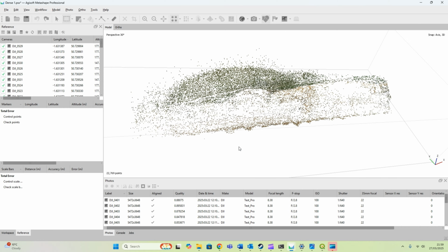At every single stage, when you add the photos in, save the project. When you align the photos, save it as something incrementally different. When you build the dense cloud, save it as different, and go through the process, be it building the DEM, building the mesh, the textures, etc. You want to be able to at least go back to your workflow, if you want to try something different, or something's gone wrong or seriously awry, you at least have a way back, a path to find yourself once again.